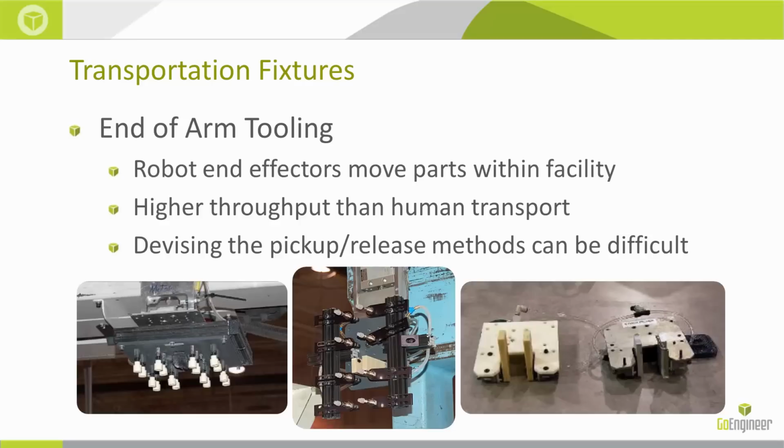Well, we could push them to the limit, higher throughput. Instead of a robot grabbing one part, we can allow it to grab 10 or 20 parts. We can also do this with plastic tooling. So, unfortunately, robots aren't perfect, mostly because humans are still programming them. So when a human programs a robot, say a 6-axis robot like what we're looking at here, it's hard to anticipate problems, but they do occur, and you crash robots.